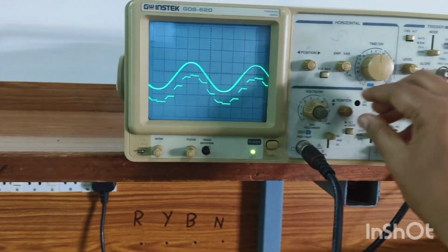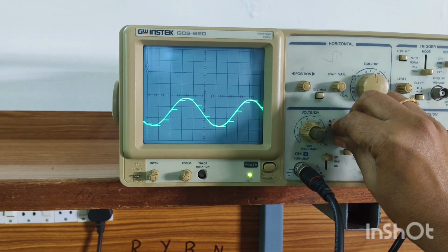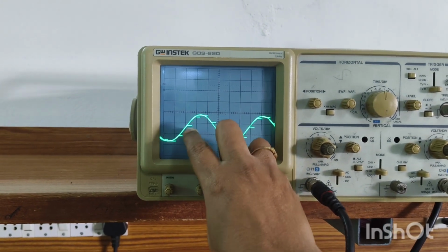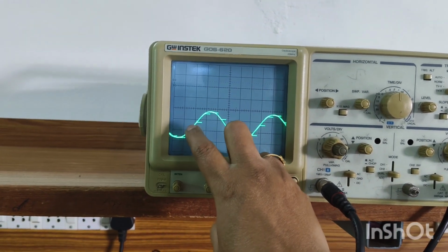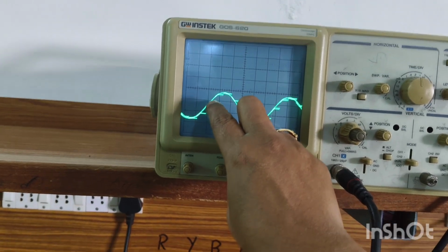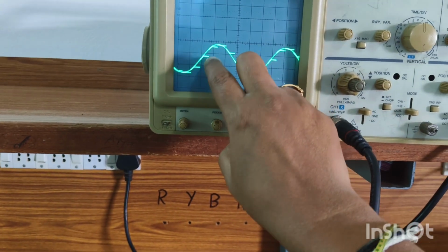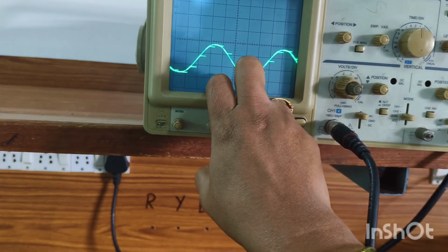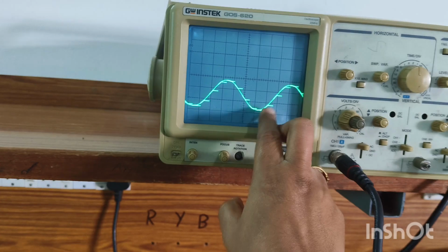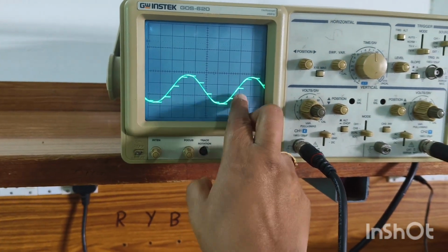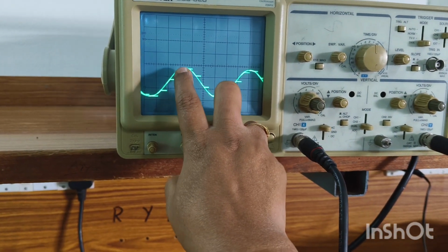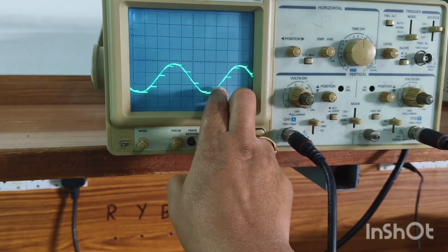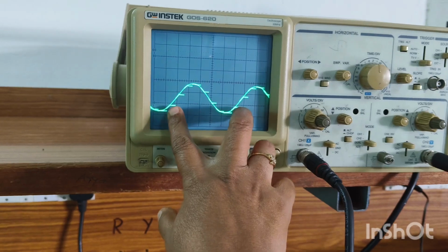So this shape is the modulating signal shape, if you observe clearly. This shape is equal to the modulating signal shape, and this is the T, the time period. Here whenever the clock is at T on, there we are going to get the amplitude of the modulating signal. Whenever the clock is T off, we are not going to get anything, that is the off signal we will get. So here for one cycle, how many samples are we getting? If you take from here onwards to here, 1, 2, 3, 4, 5, 6, 7, 8. For one cycle we are getting 8 samples.